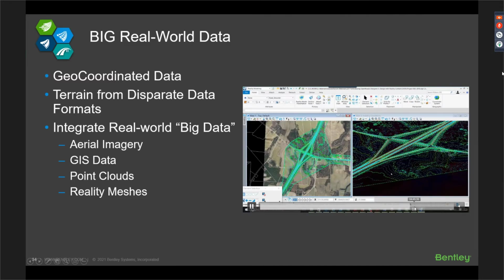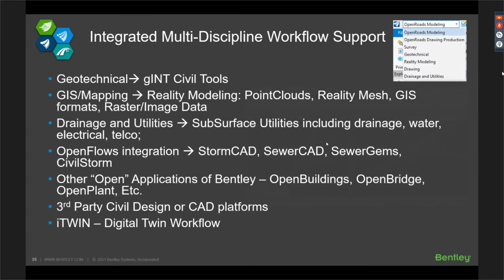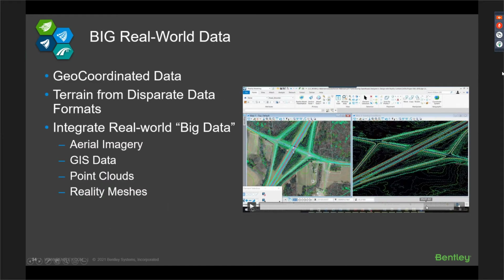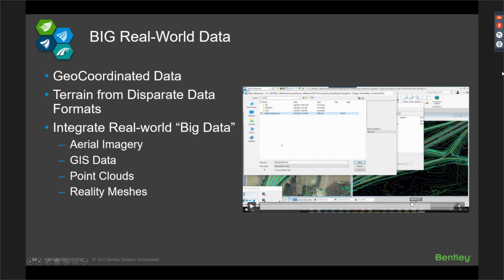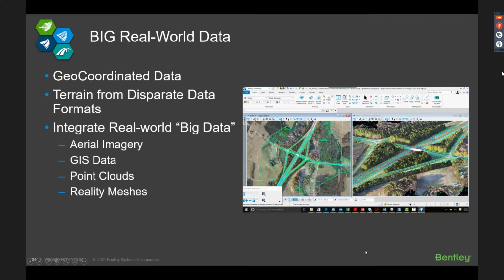And then, of course, integrating your reality models. If you're using any Bentley solution, these reality models could be processed inside ContextCapture. Oops, sorry, I pushed that too far. It could be in a format called .3mx created from ContextCapture, which is based on photogrammetry, or photos aero-triangulated in order for you to create a reality mesh. This one. Okay, so all this data or information is inside one master model.